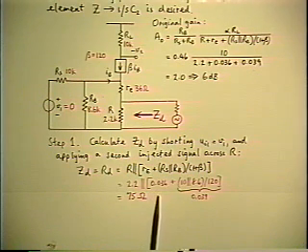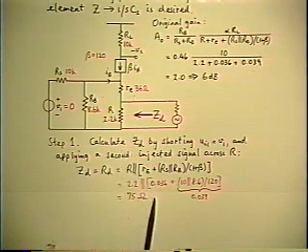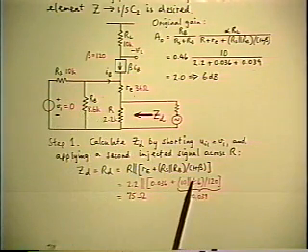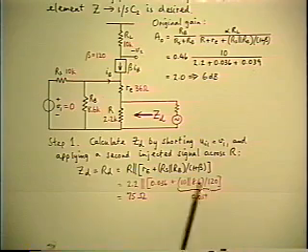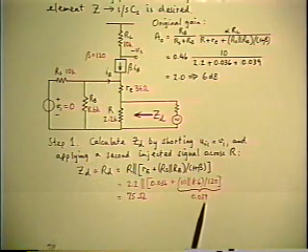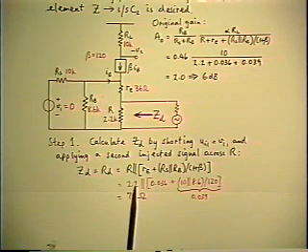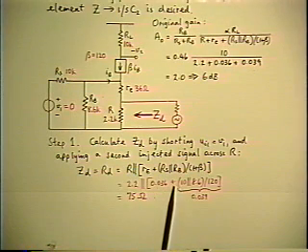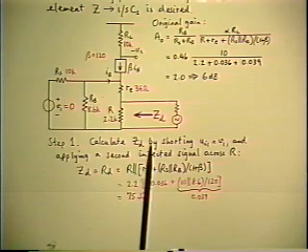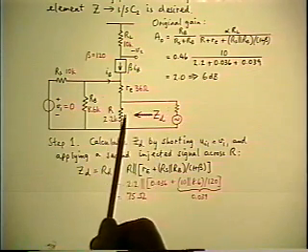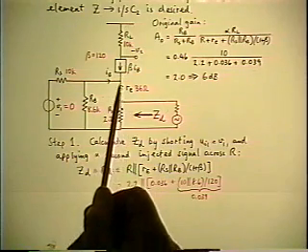Numerically, RE is 36 ohms, RB is 10 parallel 8.6, and when you reflect it, it's divided by 1 plus beta. The result is 39 ohms. 39 plus 36 is 75. 75 in parallel with 2.2K is still 75 ohms. So what that tells you is that the dominant component of the driving point impedance ZD is the path through RE.